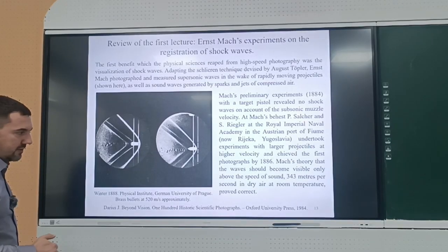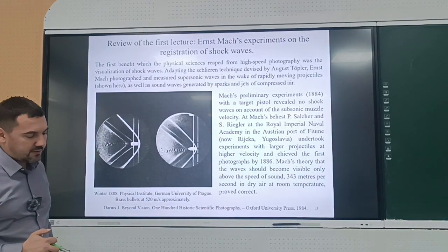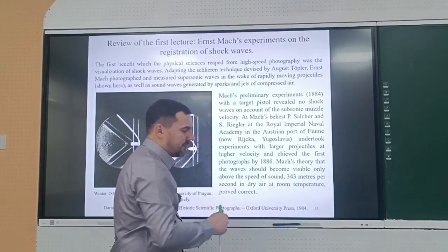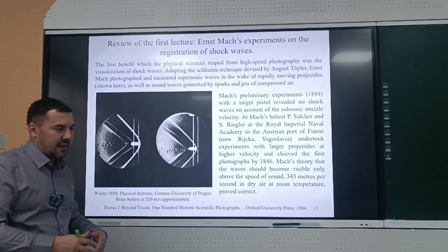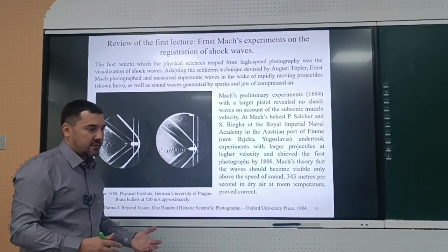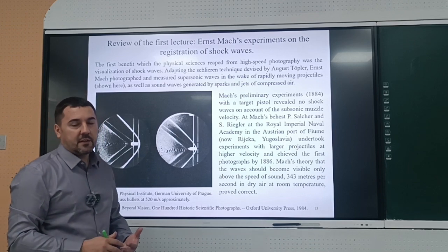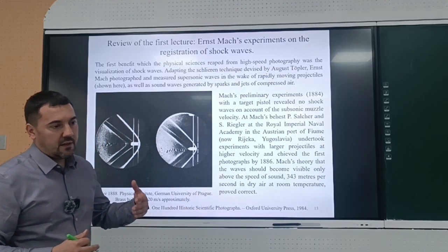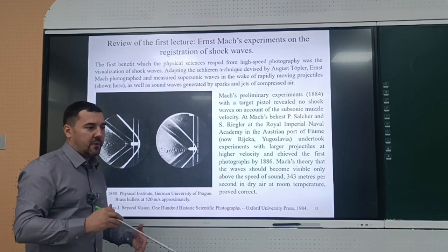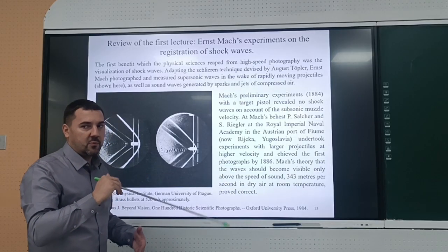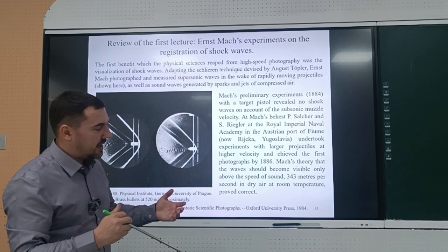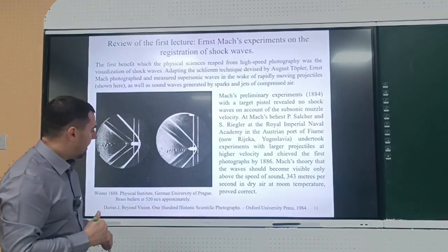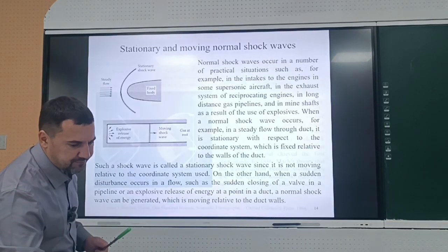Last lecture we discussed the speed of sound, and we obtained this expression. Actually, it can be obtained from rigorous mathematical analysis of the Euler equations. I'd like to remind you that we considered the Jacobian matrix of our Euler equations. Then we computed the eigenvalues of this matrix, and these eigenvalues were u minus c, u, and u plus c, where c turned out to be the speed of sound. This is the history.